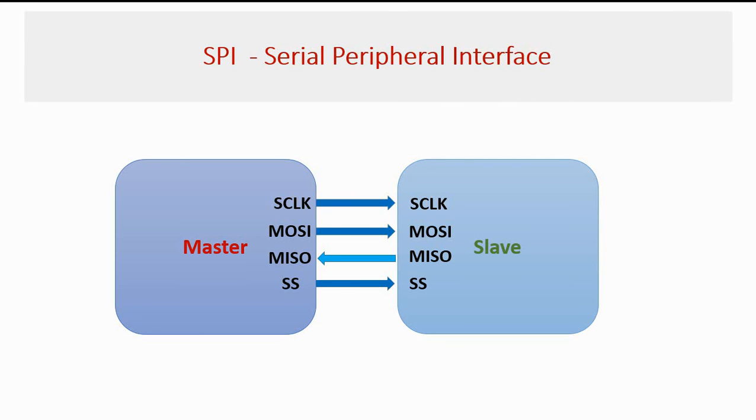Prior to the invention of SPI and I2C protocols, the engineers were generally using RS-232 communication. But in RS-232, the TX and RX pins are not synchronized with the same clock. However, they use start and stop bits and the same baud rate on both sides to achieve some synchronization. But our modern protocols like SPI and I2C use separate data lines and clock signals to achieve better synchronization.